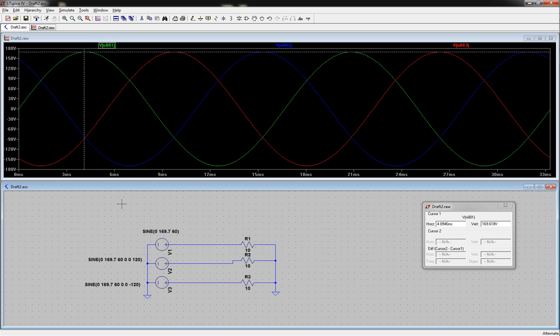Now, it won't be pretty. Like if you download a MOSFET, let's say some sort of specialty transistor that has a whole bunch of pins on it, maybe a 7-pin package, you'd have to go in and modify an N-channel schematic symbol to include all 7 of those pins. Well, if you don't want to have to mess with it, you can use the symbol generator, pull open the model file, and generate a symbol from it.